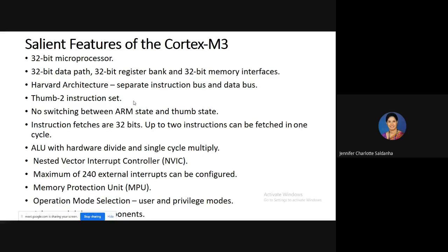Thumb-2 instruction set is used. There is no switching between ARM state and Thumb state because of using the Thumb-2 instruction set. All the instruction fetches are 32-bit, so up to 2 instructions can be fetched in one cycle if the instructions are 16-bit instructions.